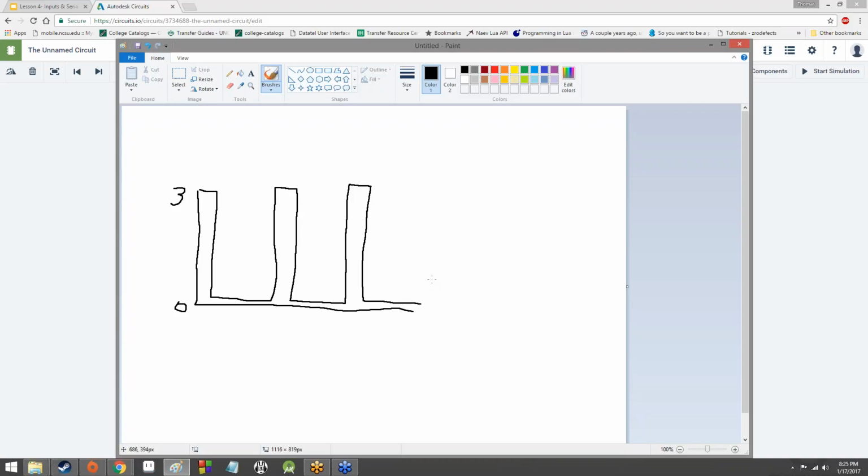This is where modulation comes into play. That's essentially just a really fancy word for control or change. Pulse width modulation is just a fancy term for controlling how long you keep something on for. So in our little thought experiment where you turn the light on and off and you don't ever let the light warm up, the light's never going to get that bright, right? Because as soon as it starts to get a little bit brighter, you turn it right back off, let it cool down, and turn it right back on, so it has to go through that whole warming process again.